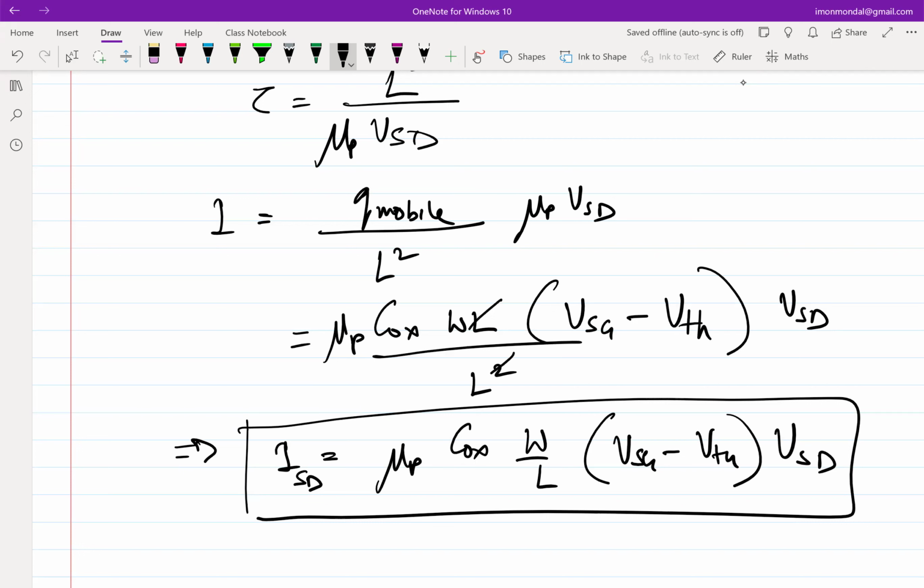Ultimately, we need an IV characteristic. This essentially is the output current-voltage characteristic. The input current-voltage characteristic was quite simple. It was 0, nothing was flowing in, but this is the output characteristic. Now, when we have an output characteristic, you can differentiate and figure out what Y21 and Y22 will be. Okay, so we start off from here in the next class. Thank you.